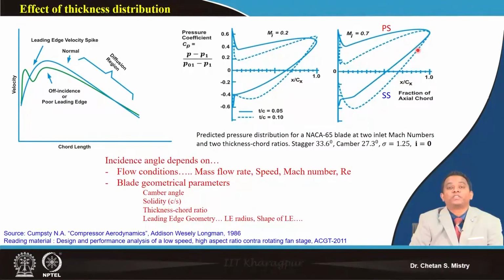Now at the initial stage when we are doing our design, we need to select one of the aerofoils for our rotor or for our stator. Then, based on what is happening on my blade surface, we need to visualize how my flow is behaving near the leading edge, and how it is behaving on my suction surface and pressure surface.